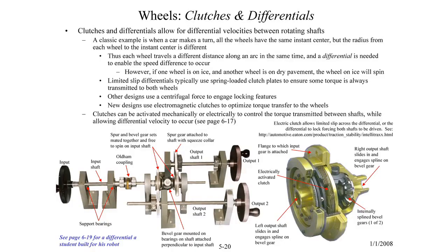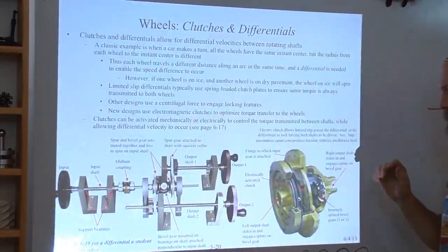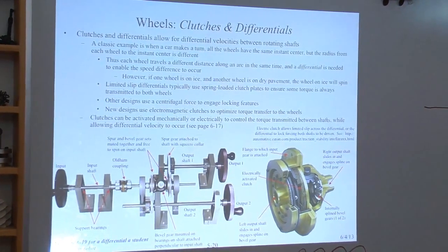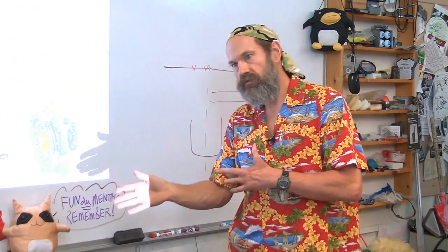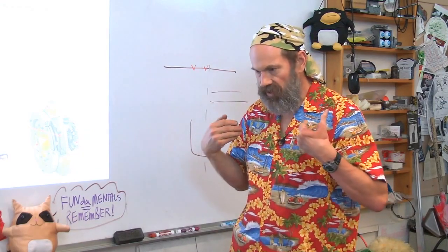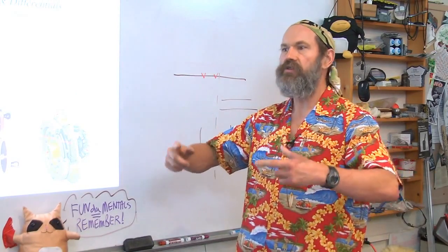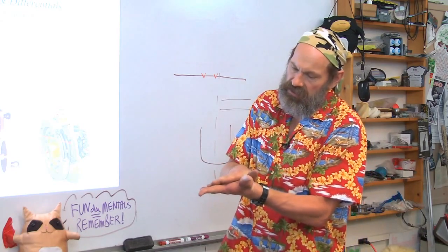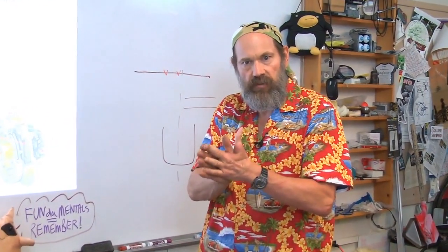Now, we just talked about the two rear wheels moving at different speeds. How is that accomplished? Because if your drive shaft from the engine and transmission assembly goes only to one wheel, that would solve the problem. Why is it going to both wheels? Well, normally under driving conditions, straight ahead, dry road, both wheels are seeing half the torque from the engine transmission. And you want both tires to see the same tractive effort so they'll wear at the same rate. If you just drove one wheel, two things would happen. First of all, your steering would have to fight that tractive effort. Why is that?